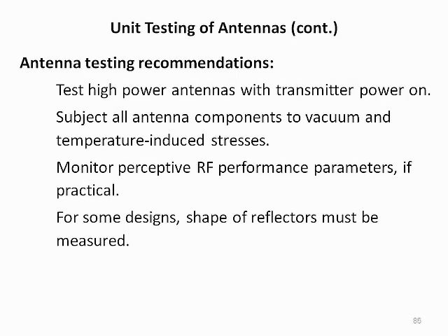A number of actions should be taken to ensure an effective test of antenna systems. High-power antennas should be tested with transmitter power on to investigate solder joint integrity and material state changes. Materials, bonds, waveguides, radio frequency or RF interfaces, substrates, and paints should be subjected to vacuum and temperature-induced stresses.